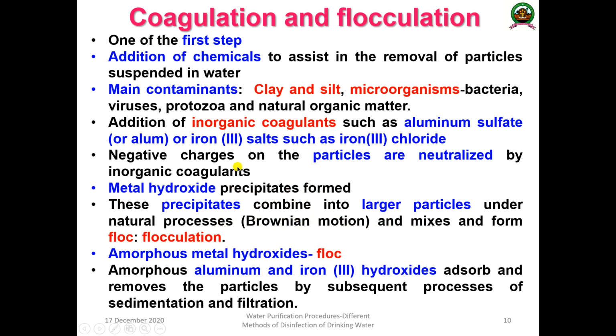So once the negative charges are neutralized by the inorganic coagulant, the metal hydroxide precipitates the contaminants, and this precipitate combines into large particles under natural processes such as Brownian motion, which ultimately mixes and forms flocs. This is known as flocculation.